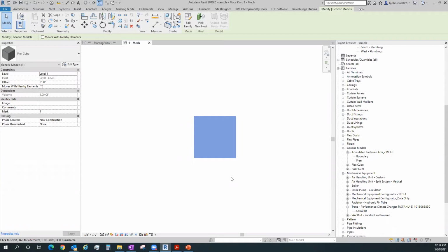So we can take manufacturer's equipment, embed them into a mechanical or a placeholder family, and then turn that into the real piece of equipment or light fixture or whatever we want. But usually, if you've got more than say 4 or 5 parameters, I probably wouldn't necessarily do that. I'd probably just load my real shared parameters into the family in that case and not have to think about doing links from one to another. So a lot of good theory in how to create a good family.